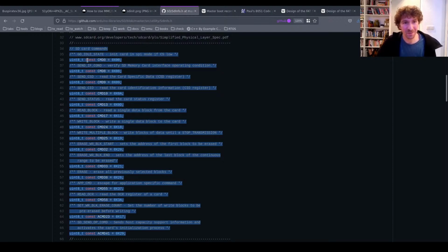And it's funny because the const keyword means something completely different in C and C++. It literally means this value won't change, and in the case of microcontrollers, it means the compiler can do special things like, oh, I won't actually make space in memory for this because the value's not going to change, so I can just use the value instead. So it's a good way of making a well-defined, well-typed name.